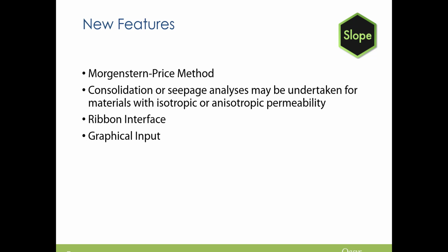But additionally, we've got the Morgenstern-Price Method, which has been requested by the Australasia region. We understand it's heavily used there, but it is used elsewhere as well. Consolidation and seepage analysis can now be run because pore pressures can be calculated as well as specified. We've got the ribbon interface, which is a new interface that I'm going to show you today, and the graphical input feature is just really quick, and I will show you how to run with that.